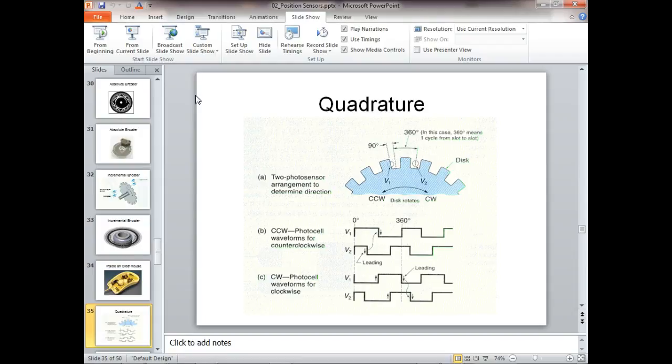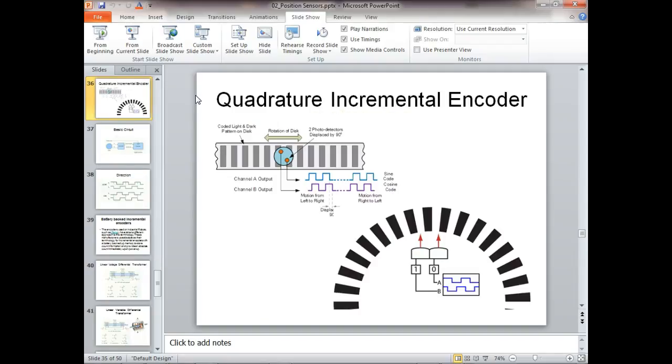the falling edge. And they say, okay, if this is low, and this is going low, and this is low, then that would be 1 count. Go in this direction, right? You understand? But over here, when this is going low, this guy here is high, and it would indicate the what? But it's looking at both of them, right? You understand? So instead of looking at one, it's looking at both of them. You understand what I'm saying? Pretty neat. So using a quadrature encoder, even though you're only running in one direction, would eliminate a lot of